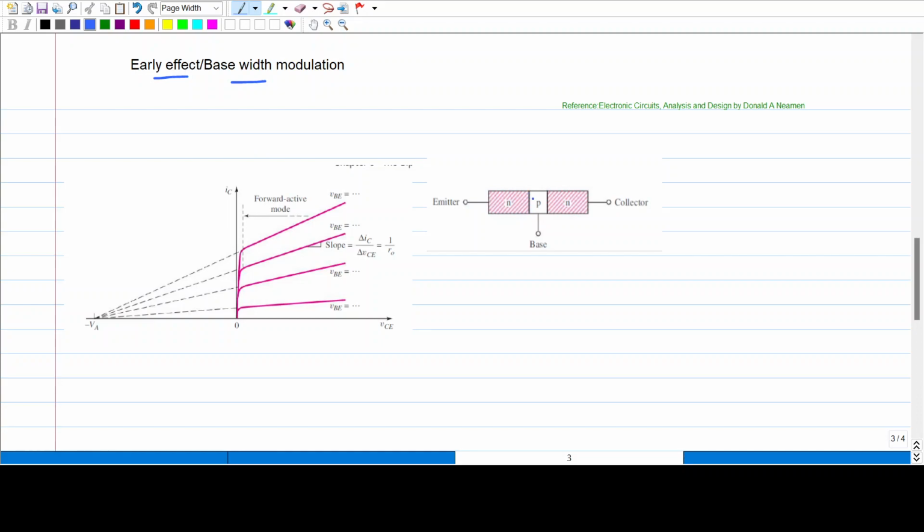We can see this is the emitter base junction and this is the collector base junction. Now I will draw this collector base junction alone. This is the P side and this is the N side. This is the depletion width. And here is the N side. What happens here is electrons are injected from the emitter into the base, and whatever electrons approach the collector base junction will be swept across the junction due to the strong electric field in the depletion width.